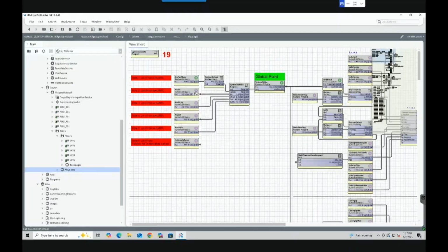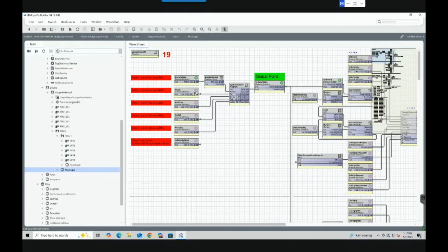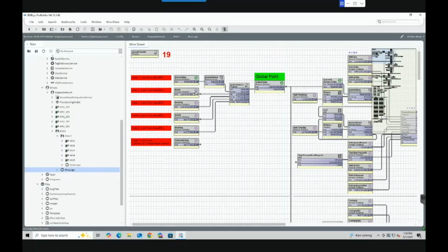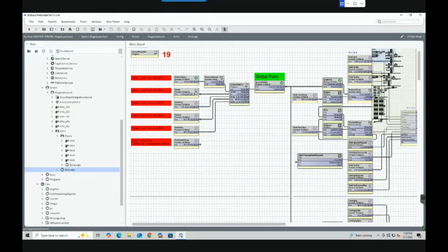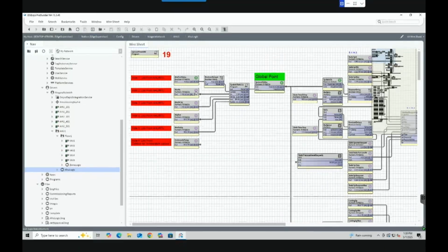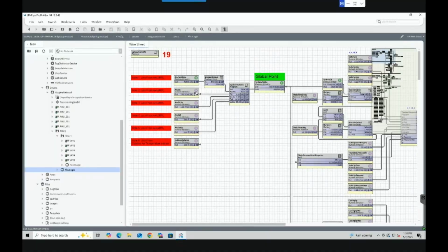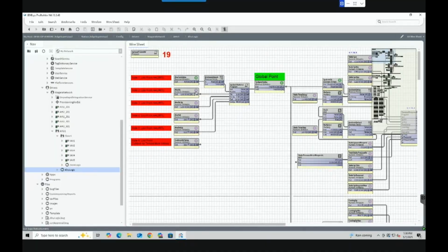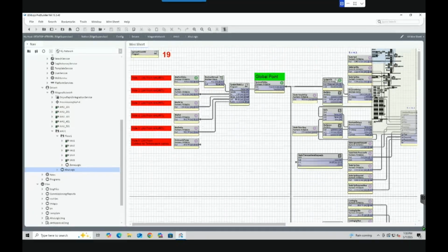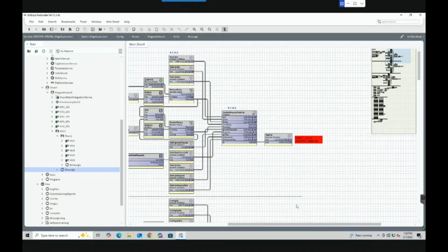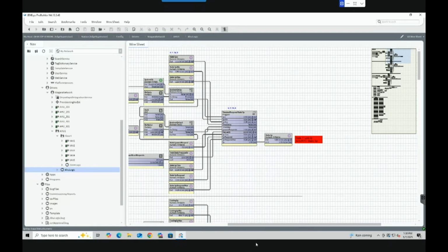So the logic in the zone will actually do all the scheduling for you. It'll do what I like to call the trim and respond program. So it'll do your static pressure reset and your supply air reset based upon heating, cooling, or pressure requests as per the G36 guideline. Now, should you want a non-G36 application, we do have them and we provide them with our VAV download. So again, you just follow the notes, follow the bouncing ball like Disney sing-along. You'll just link everything together.